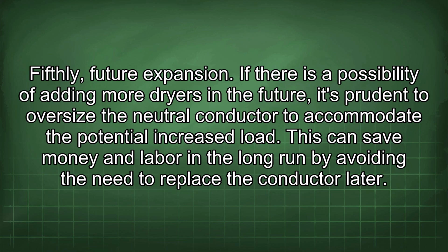Fifthly, future expansion. If there is a possibility of adding more dryers in the future, it's prudent to oversize the neutral conductor to accommodate the potential increased load. This can save money and labor in the long run by avoiding the need to replace the conductor later.